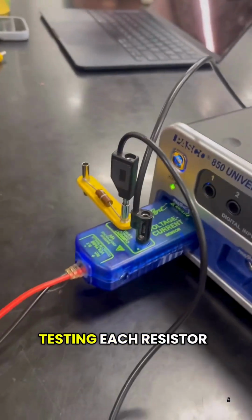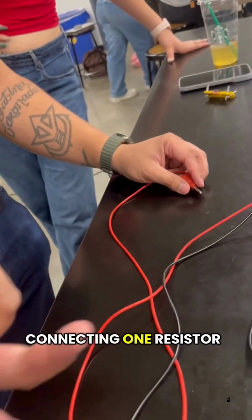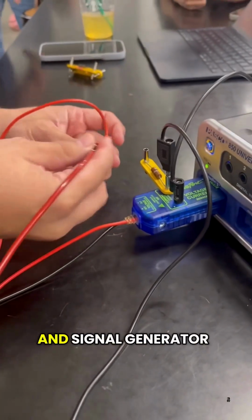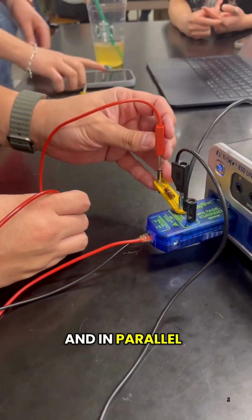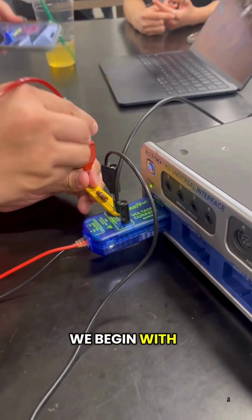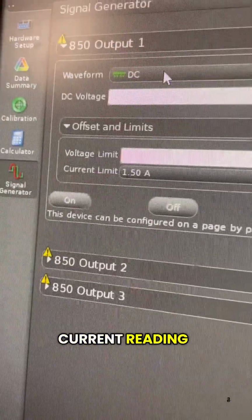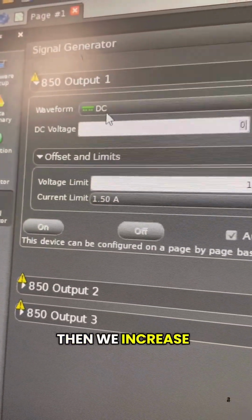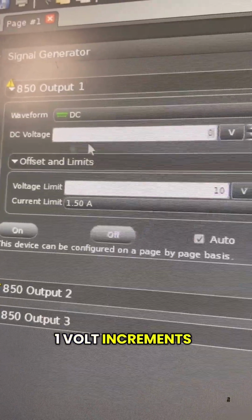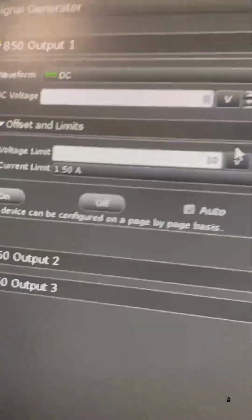We start by testing each resistor individually, connecting one resistor at a time in series with the current sensor and signal generator, and in parallel with the voltage sensor. We begin with 0 volts on the signal generator and record the current reading. Then we increase the voltage by 1 volt increments, continuing until we reach 10 volts.